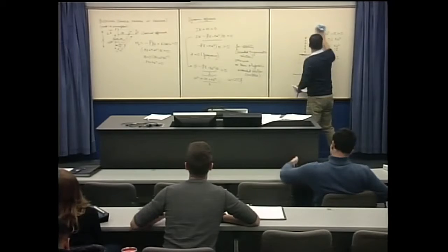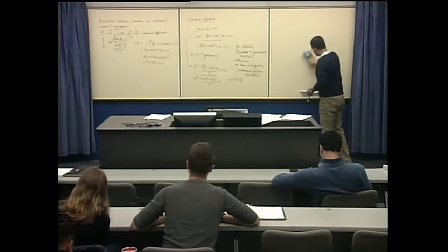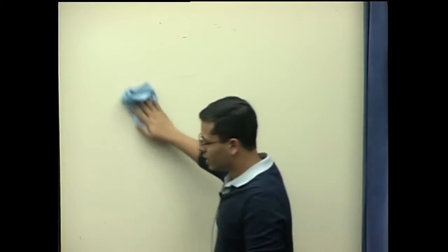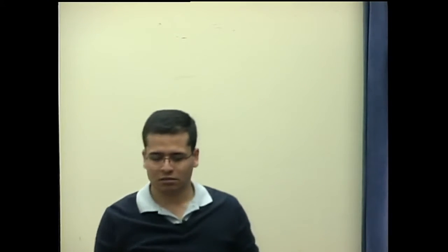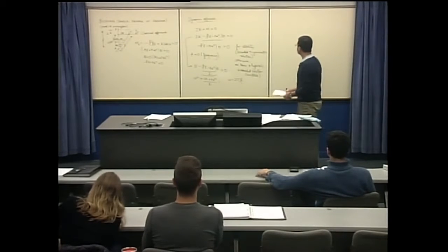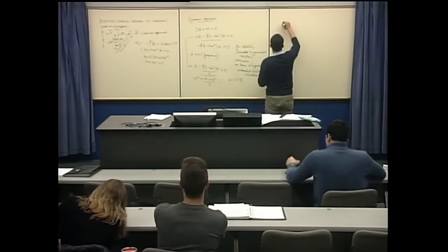So these methods are possible or feasible to calculate equilibrium positions and the post-buckling path, but they become very complex if we have, let's say, large trigonometric expressions or nonlinear equations. Especially if you consider large deformations, the dynamics approach becomes highly nonlinear. So we'll stick to the energy methods and would consider large deformations in that problem.